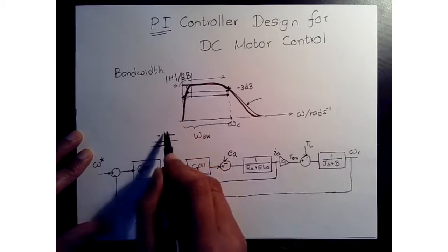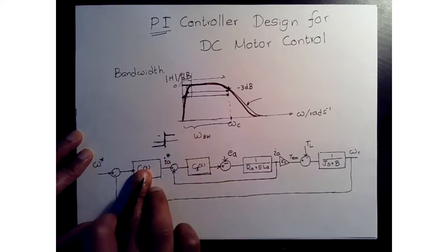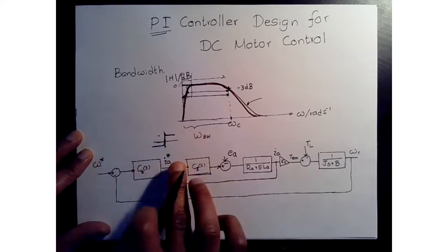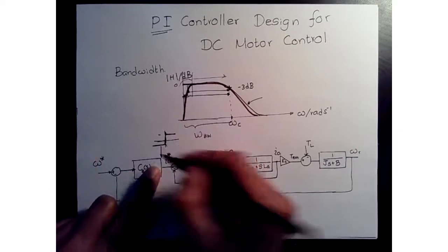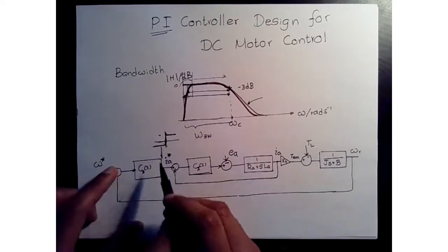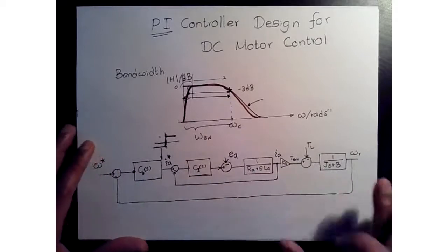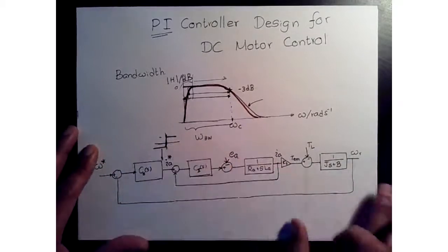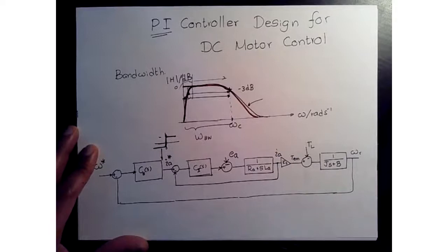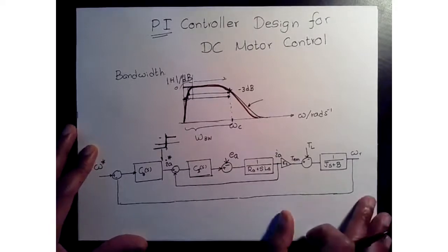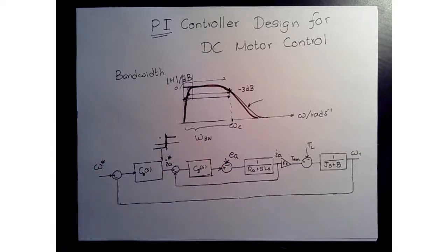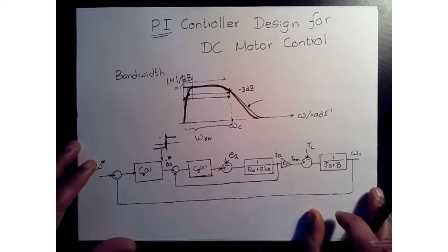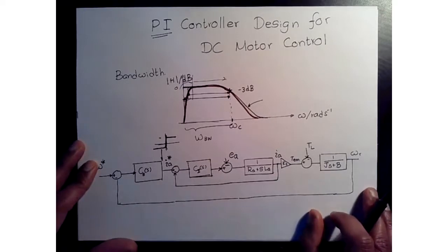You can set that limiter block in between the speed controller and the current reference, in between these two. So it goes right around here. In the simulation, not having this is fine, but in practice you might go into a very large current command, and then your battery voltage might drop, and that could induce other issues into your system.